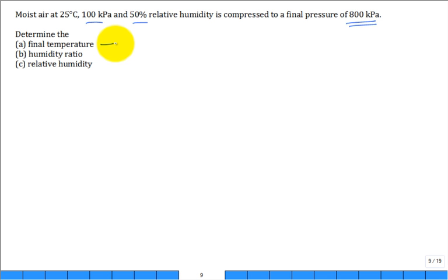But if you just wanted to make a quick calculation, I would do this. I would say the final temperature after compression is the initial temperature, times P2 over P1, how much was the pressure increase, to the K minus 1 over K. True? And you can do a lot of work to get the K of the mixture, and you can compare that to the K of the dry air, but because there's just not that much water vapor in the air that we breathe, remember by mass, even for a really moist system, it was like 1 or 2%, this basically is going to be around 1.4.